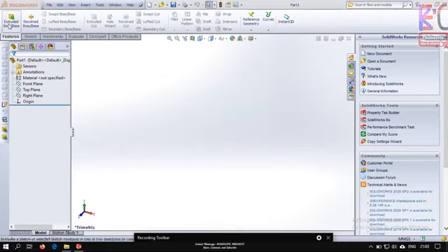Let us consider, click on this Extruded Boss/Base. We will not go for this one. We could also make symmetric objects with Revolved Boss/Base, but there is one criterion for making a symmetric object: it should have a center axis about which it will revolve 360 degrees. I'll teach about it afterwards in the next class. So in today's class we'll learn about how to work with a basic Extruded Boss/Base. Let us click on this.